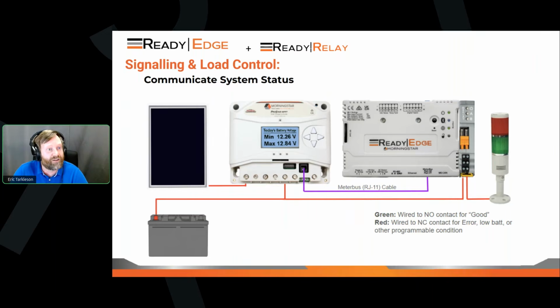And when there is an error, which could include low voltage, which would be an alarm condition, so faults, alarms, errors, then it will turn on that relay and you'll get a red light. So if you're driving by because you're a Department of Transportation on the freeway and you see a red light on top of the box, you know that you have to stop and check that site or alert somebody else. And you can do that either on site, or send the same information to a PLC or SCADA system, or use Solar Connect to get the same information online.